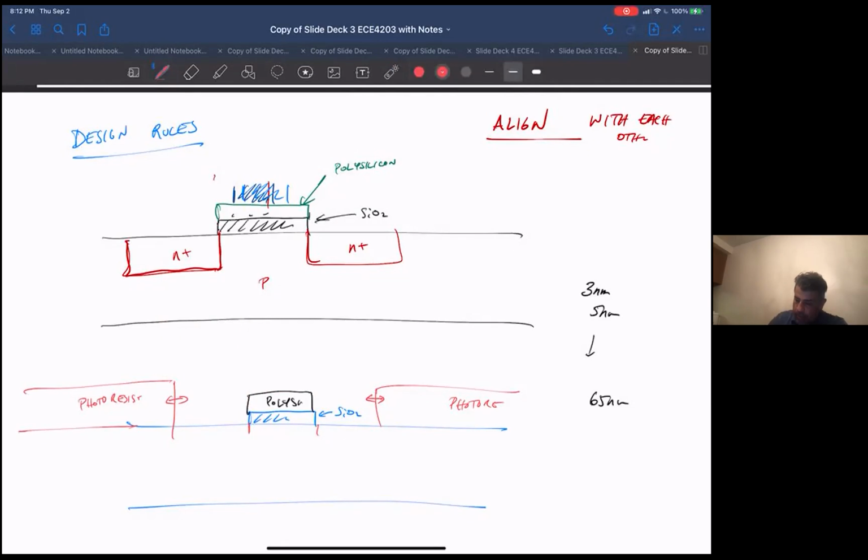the polysilicon makes sure that the N+ ends up exactly on this edge, because the polysilicon itself ends up being the mask for the N+, and it makes sure that there's no N+ underneath it, and then it makes sure that the N+ is here. Now again, there could be some movement here because the photoresist isn't printed necessarily that accurately with the polysilicon, but you don't really care about this region here. That won't affect you much at all.